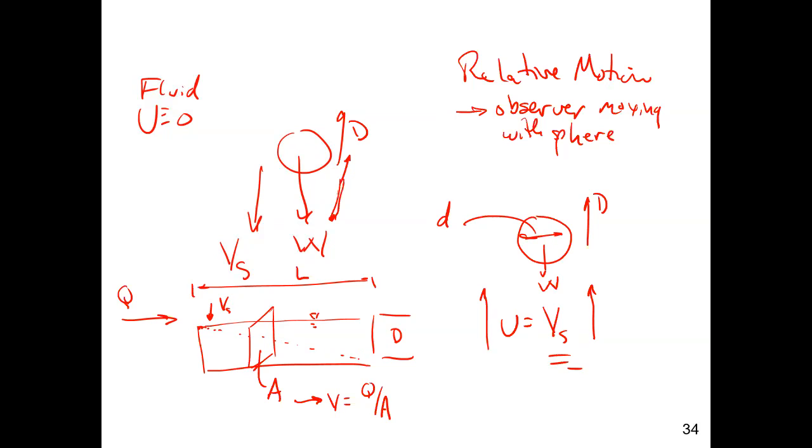And so since you know the velocity and you know the length of the tank, the settling time is equal to L over V. That's how long it would take water to move from the left-hand side to the right-hand side. And what you want is the time it takes the particle to go from the surface all the way to the bottom has to be a time that's less than that. And then you'll settle out that particle.